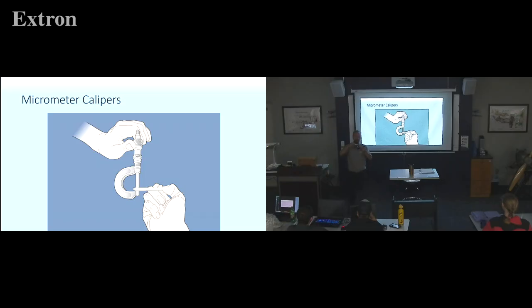Are you allowed to turn the barrel at all? Yes, if you're needing to make coarse, big movements like this, big movements, fine. But then when you get the part in there, or whatever you're trying to measure, you just turn till it clicks, okay? So you're saying if it tightens onto the thing, you continue to turn the big barrel, then it'll move inside. Yeah, and the thing that's annoying is when you're doing the big barrel part here, the main barrel, if you're doing that on a telescoping gauge, the telescoping gauge has a spring in it. And you wonder why the springs don't pop out anymore, because somebody's going, not clicking, because you're not doing it correctly. Okay? All right, I'm venting, sorry.